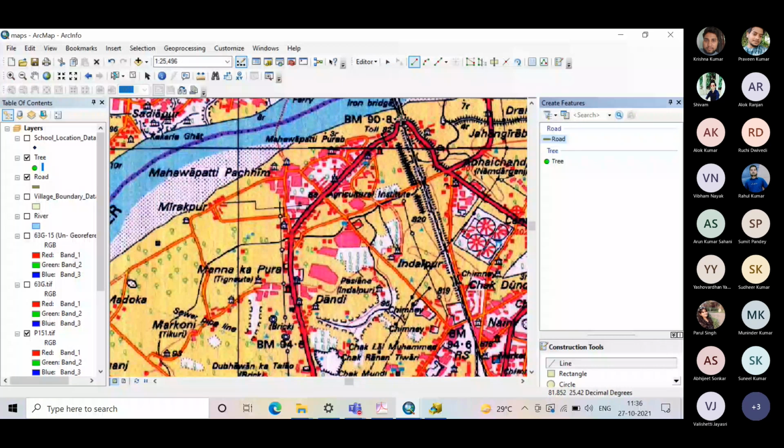There is a variation: in some places it is simply a point, in some places it is simply coordinates, in some places it is nodes and vertices. So you must know all these terms. Right now, as you can see on the screen, I have this cross here, and I'm going to start to digitize this road. I am placing my first point, I have clicked, and first I need to zoom in properly. Whenever digitization is performed, it must be zoomed in properly.